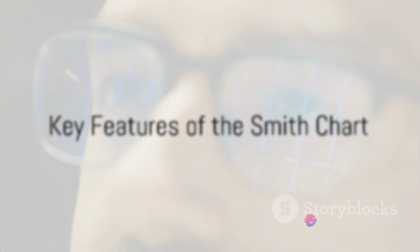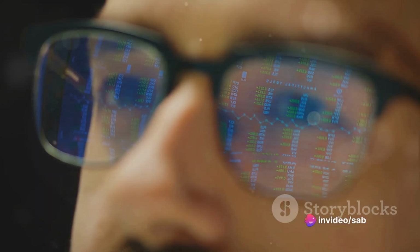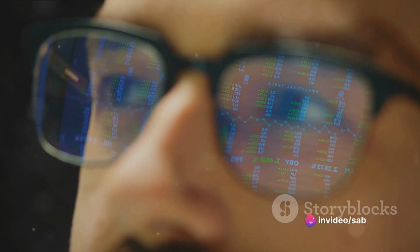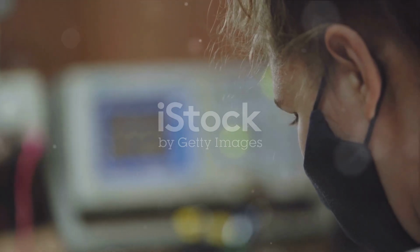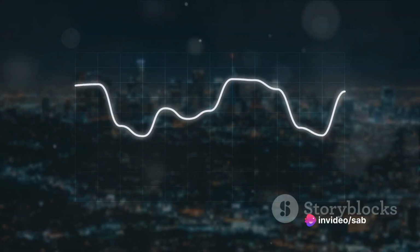But what makes the Smith chart truly remarkable are its key features. First off, it can calculate the reflection coefficient of a given impedance. This coefficient shows the amount of power reflected from an impedance mismatch. By locating the normalized impedance on the Smith chart, the corresponding reflection coefficient becomes apparent.